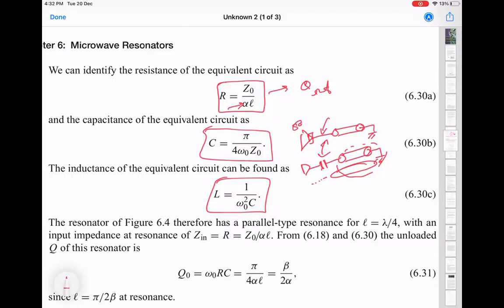It's not always true. I can give you an example of one of the experiments we did where you do operate far away from the resonance, and there's an implication which is related to the fact that the model we use of a simple LC circuit doesn't predict the correct results when the frequency is far away. We have to use a more accurate model. But software like microwave office or even finite element software can do that. They can give you the correct frequency response. But what you will see now is how that frequency response changes as you go away from the ideal operating point.